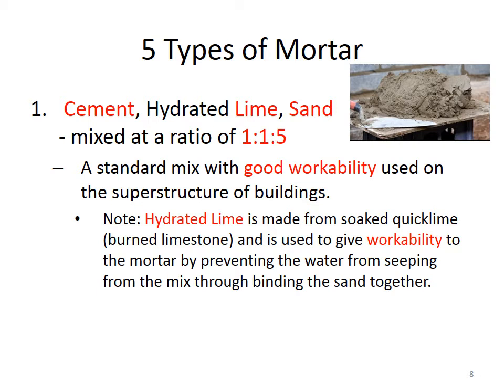How it does this is by preventing the water from seeping from the mix once it's mixed up. The lime binds the sand together. The hydrated lime is quite sticky once it's wet, and so it helps bind the sand particles together, which in turn helps hold on to the moisture to make the mortar more workable.